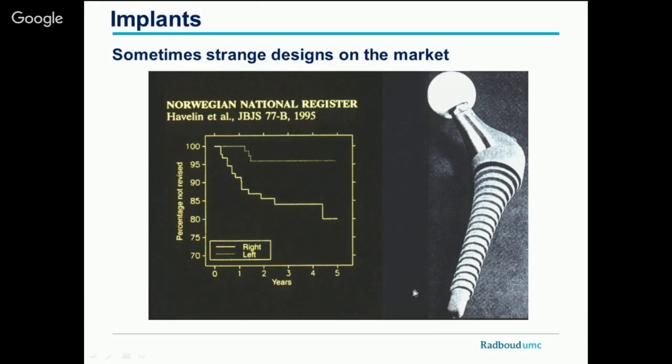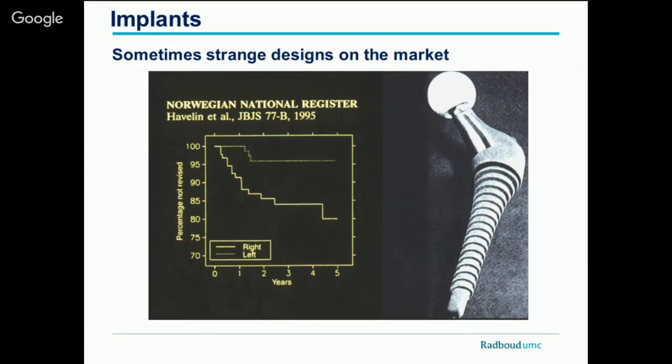Why would that be? I give you a hint. The screw is only one-sided. Yeah. So the force in our joint is coming also a little bit from the front. So on the left side, it fastened the screw. On the right side, it loosened the screw. Yeah. So from a mechanical point of view, that is really a little bit naive, huh?